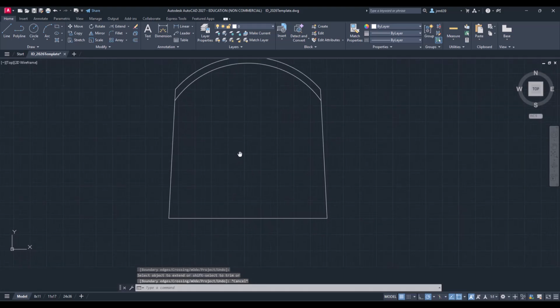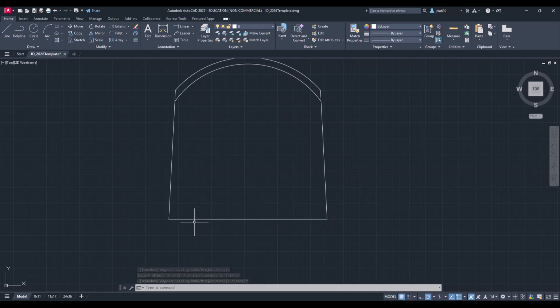And then the last thing that I'm seeing is that these are awfully sharp, and it's no fun when you scratch the back of your knees when you're sitting in a chair. So let's make these corners rounded. And what's the best tool to round corners? It's the fillet command. So let's use fillet.